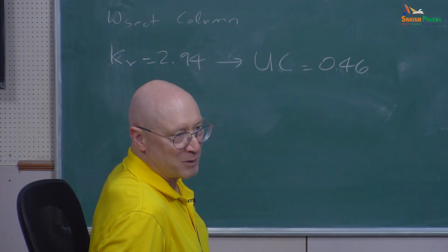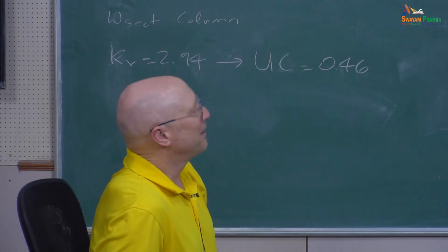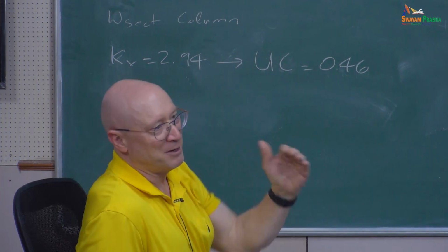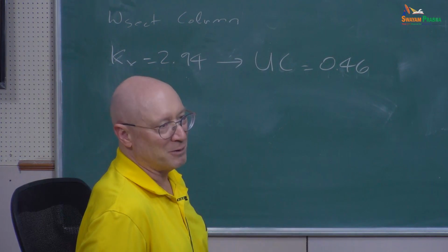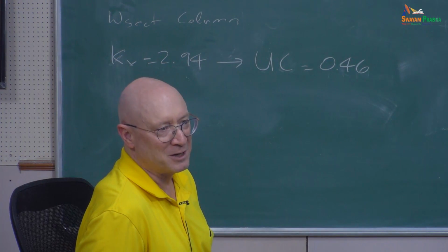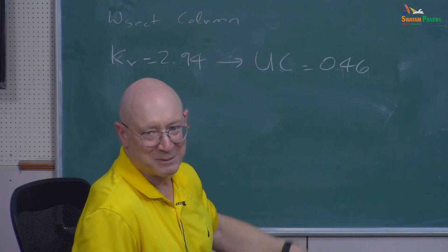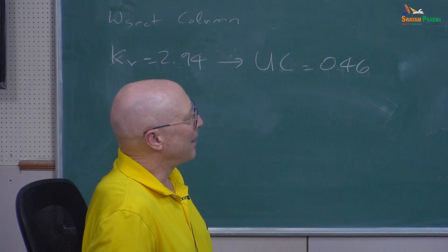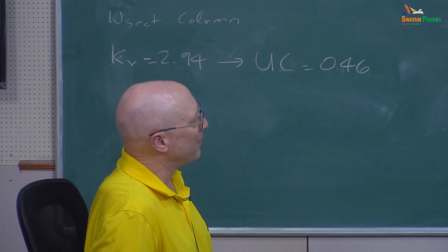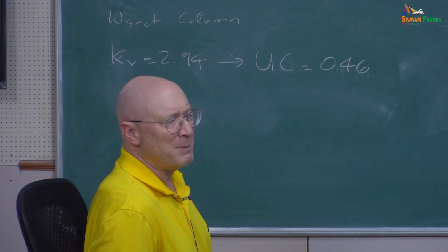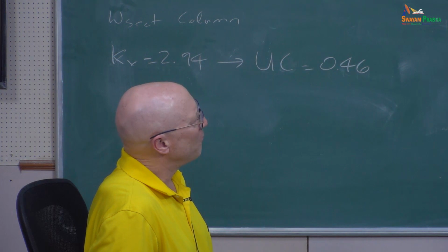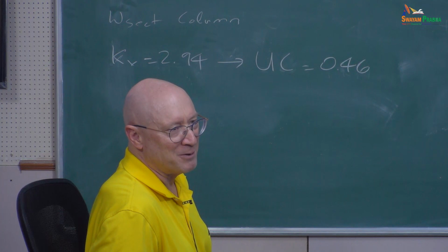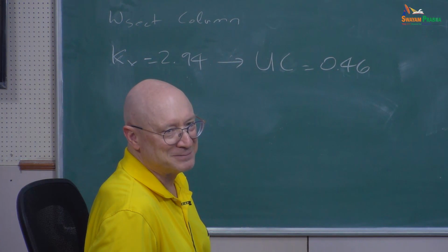It's just that if you get to a very high moment demand on the base, it's nonlinear, and so this is kind of trying to give a very simplistic secant approximation for the base rotational stiffness. So given this, you could probably just say, okay, maybe we'll make the wall of that HSS section a little bit thicker, and then it's going to work.